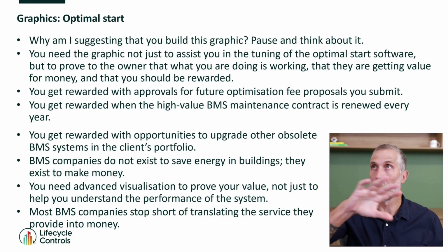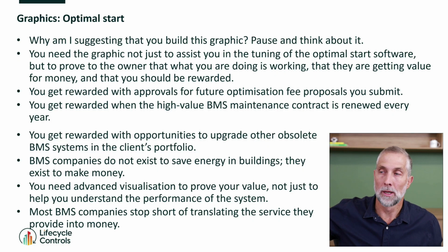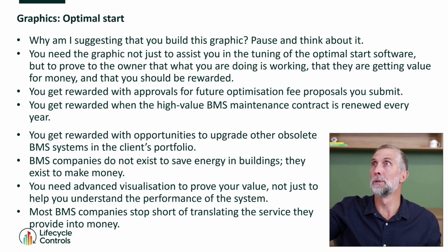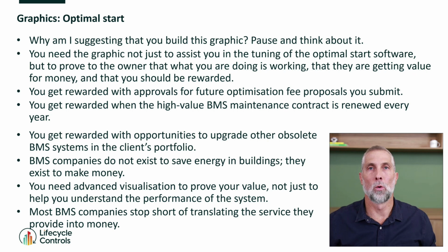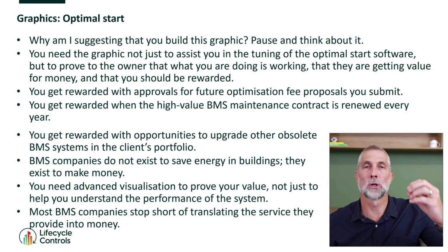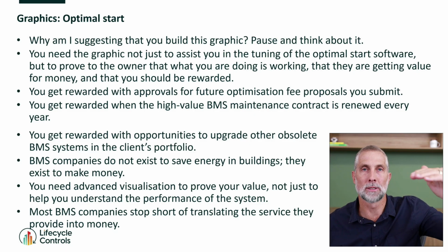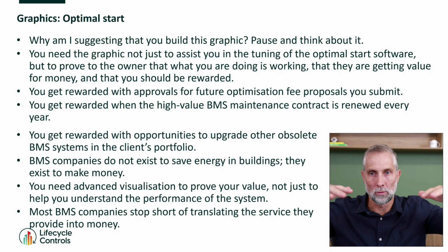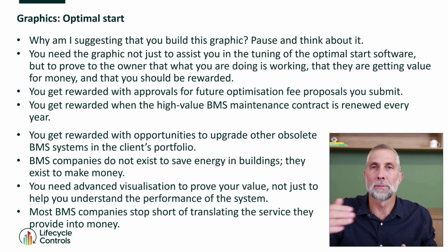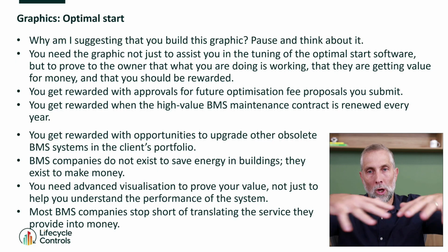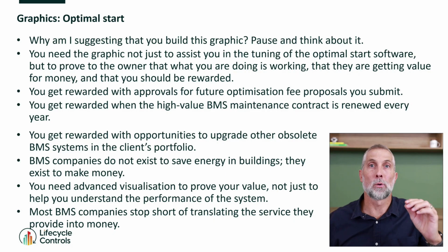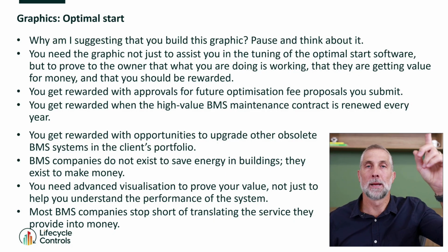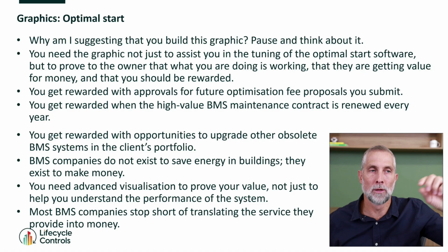You've got colder air going through the duct system and down the floors, 2 degrees colder air blowing out of the diffusers. And the VAV temperature sensor on the wall detects that cooler air coming through, and the VAV damper closes slightly, because it needs less cooling. All of the VAVs close off slightly, 5%, 10%, 15%. The air handling duct pressure goes up above set point and the supply fan slows down and the return fan slows down.